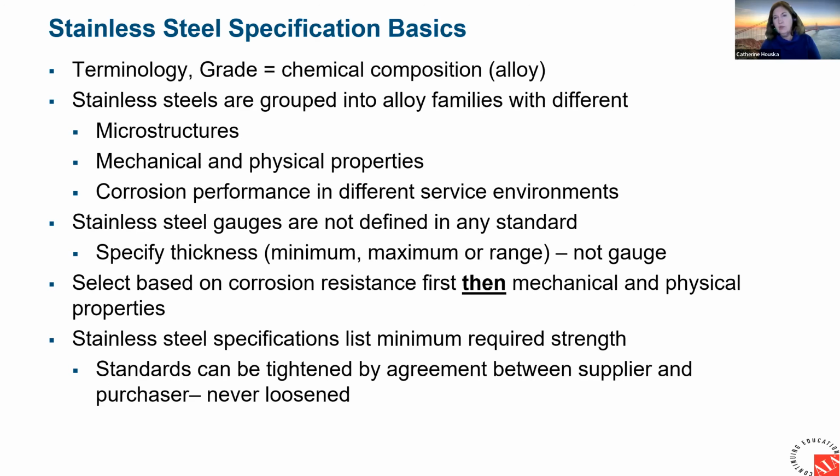It's also critical to understand that stainless steel gauges are not defined by any standard, and they can be a bit different from one stainless steel producer to the other. On top of that, if for example, somebody was talking about 10 gauge stainless steel, well, that is not the same thickness as 10 gauge carbon steel. So please make sure you specify the actual thickness that you want. Don't use gauge numbers.